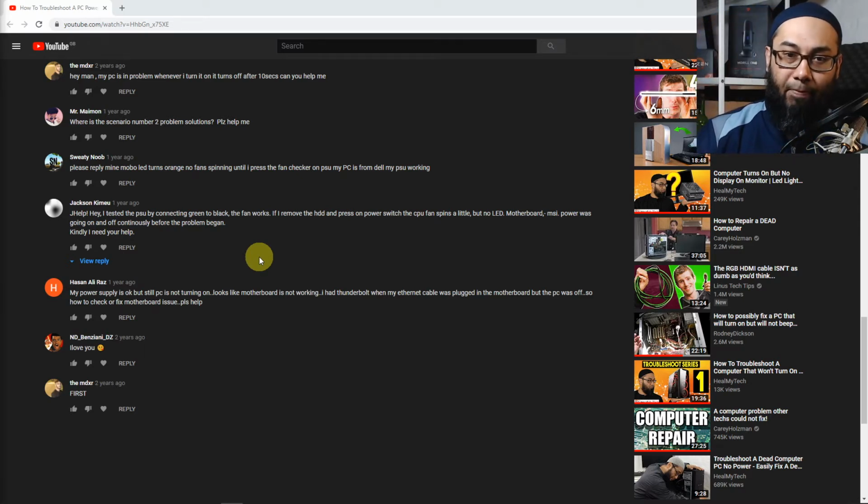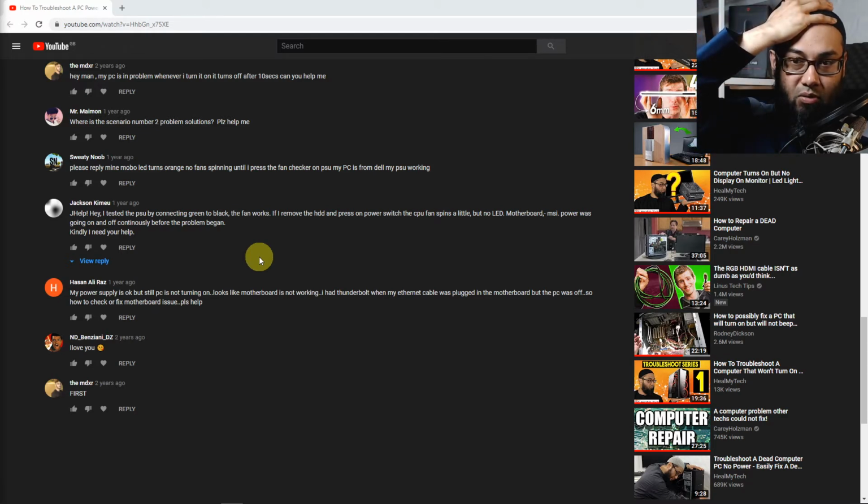Right, so you've done the PSU paperclip method. So all that tells you is whether your power supply actually turns on or not. Is it completely dead, or does it have some life? Again, like in this video we mentioned, what it's not going to tell you is whether it's delivering the correct voltage. But even if it is, I would advise you, because you're not sure, you need to find a non-working power supply, because you have to eliminate the power supply as the issue. And then you're talking about, if I remove the hard disk drive and press on power switch, the CPU fan spins a little but no LED.